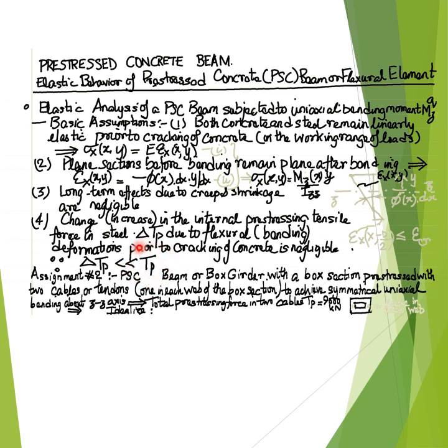And thus, the internal pre-stressing tensile force in the pre-stressing steel, in case of the pre-stressed concrete beam, can be assumed to be constant and equal to the original pre-stressing tensile force Tp, that is induced by the pre-stressing operation.